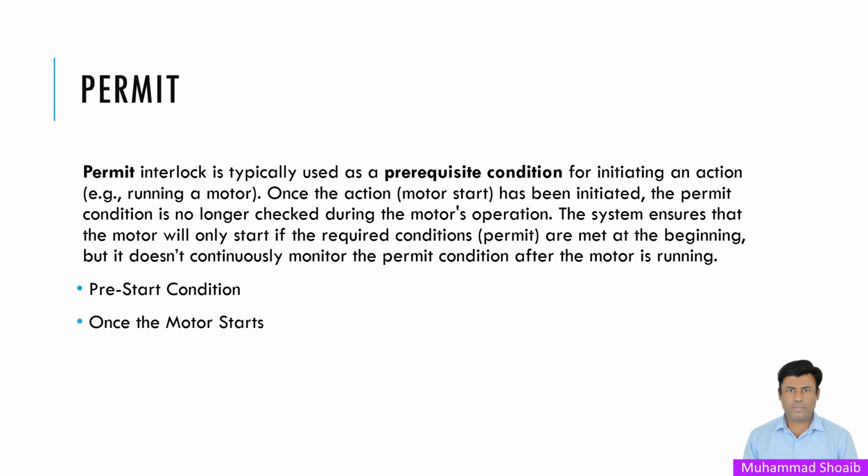Once the motor is started, the system does not keep checking the permit conditions. The motor will continue to run even if the permit conditions change. Shortly, we'll see this practically also. Unless a separate interlock or protection measure is in place to shut down the motor.